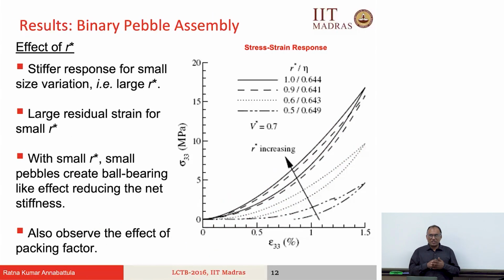It is not only friction. Friction is one aspect, but there is another aspect. The particle might be moving from one equilibrium position to another equilibrium position during loading. When you are unloading, the particle which has moved from one equilibrium position to another may not have the driving force to go back to the previous equilibrium position, although there is no frictional dissipation. That is also a reason why the unloading path may not be the same. It is not only because of friction.